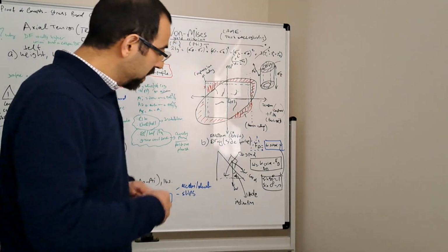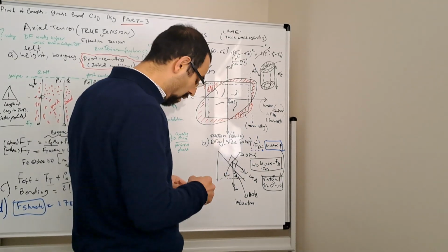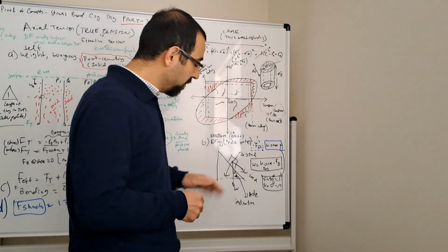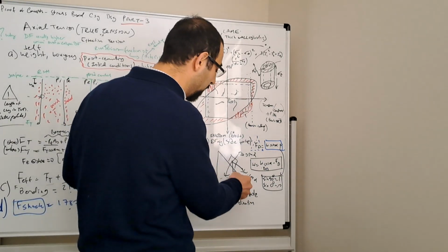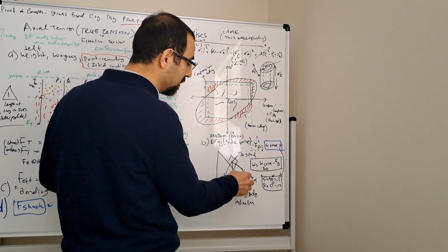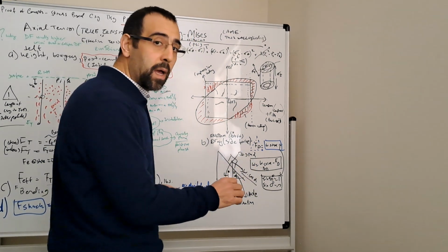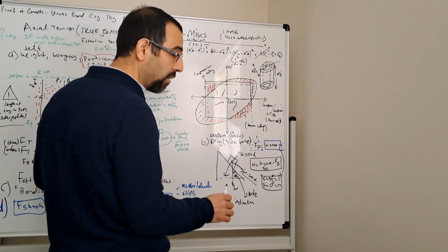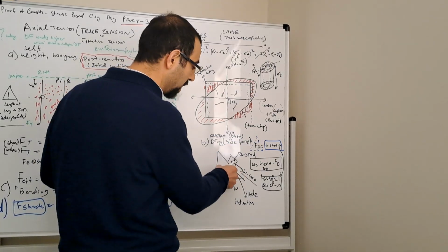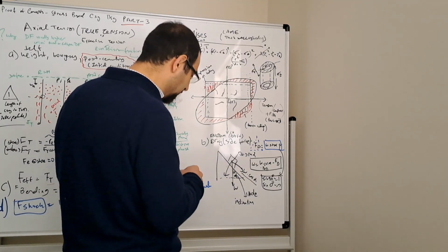So if we say an inclination of the wellbore, in a very simplified version, is alpha, then I would easily calculate that weight times cosine alpha is the weight basically acting along the hole, and then my side force, the perpendicular one, is the weight times sine alpha.